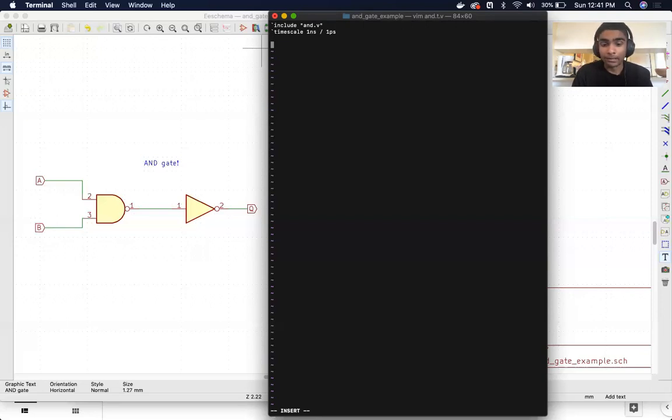Okay. So now let's make a module for our test bench. So module, nothing new there. We'll call it NAND2_test. What we need now are the inputs and the output for this test bench. To do that, we're going to use this thing called a register. We use the command reg, and then we list out all our registers like we would anything else in Verilog.